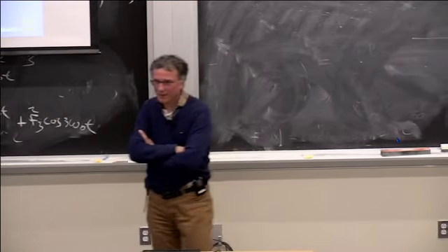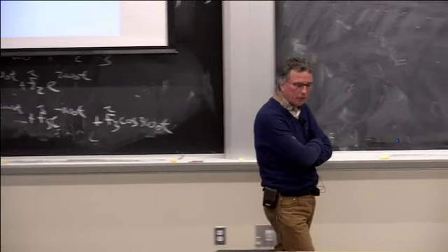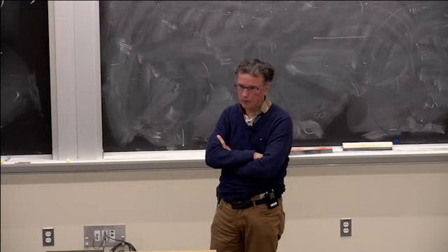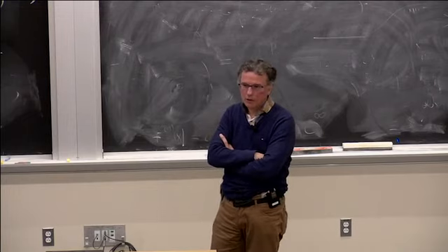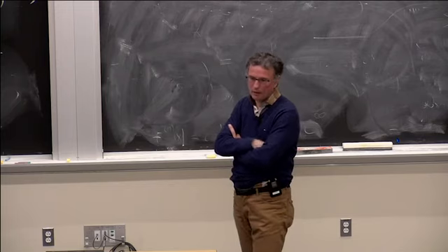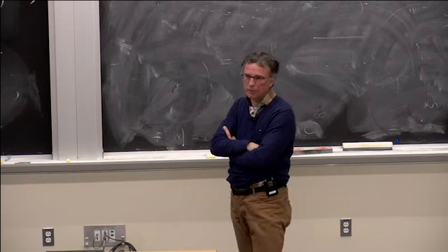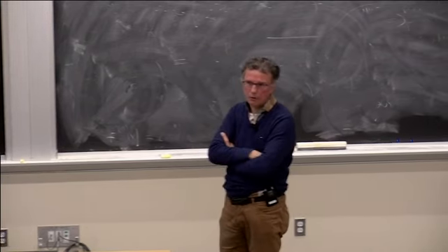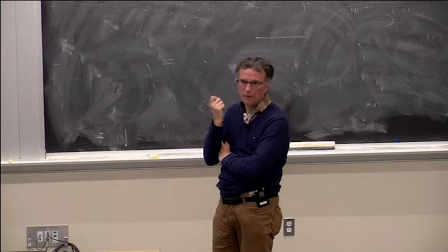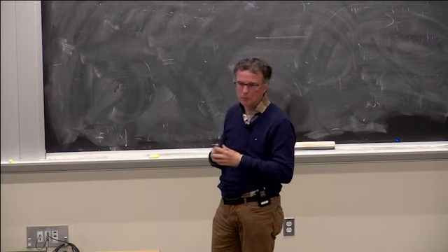So what is the typical frequency of light rail lines? A minimum is 4 light rail vehicles an hour each direction. That's the minimum. Otherwise, it goes up to 6 or 8 in Delft. And in other cities it can be more. But 8 is pretty much for a city with 100,000 people. And it has to compete with cycling. So many people who cycle, you take them out of the public transport system.